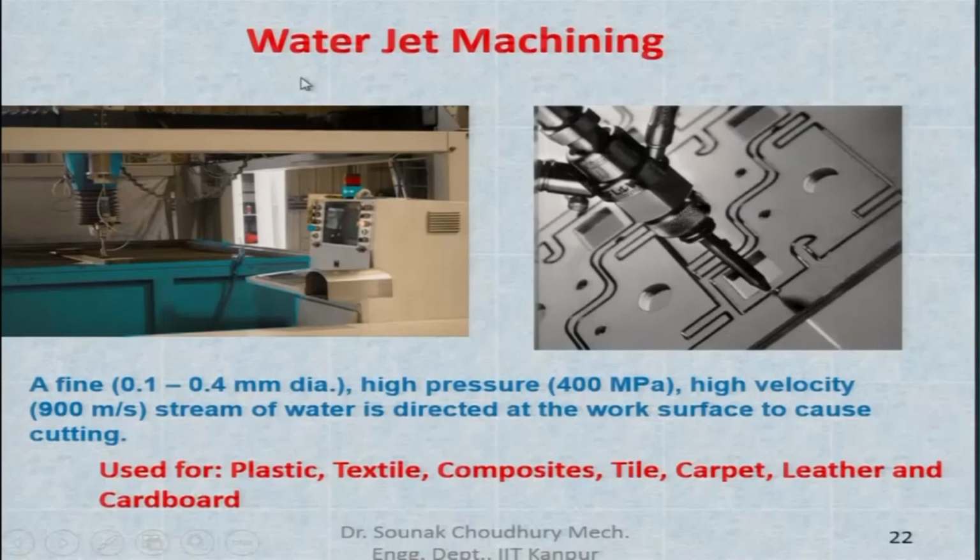So, here, as I was showing you in the last session, there is water jet machining. Here the very fine water jet impinges the surface, and it can actually make a through hole within this width. You can see the width of the workpiece shown here. So, this is the kind of grooves or slots that the water jet can machine by moving that water jet along this path.